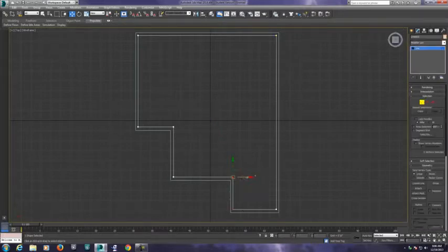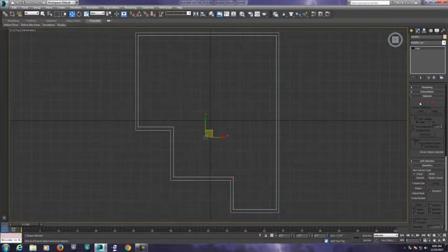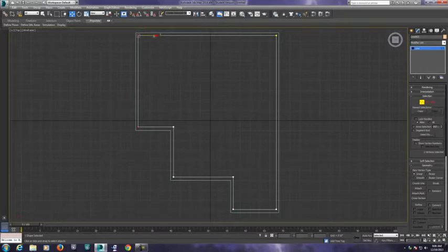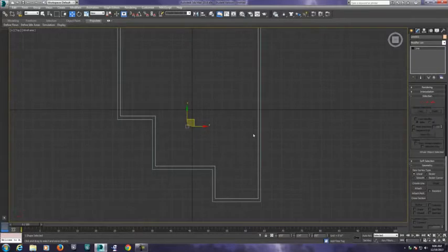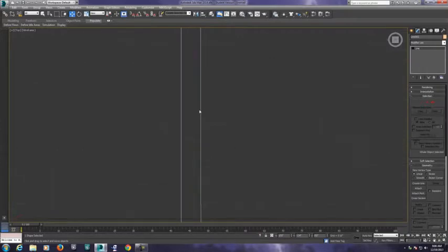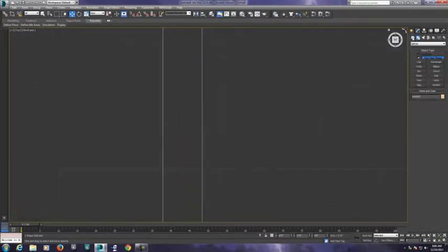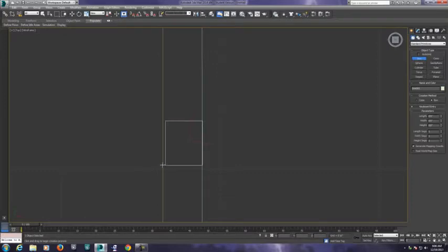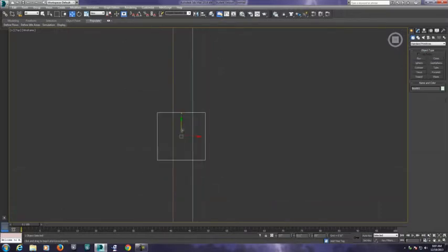And again, if somebody gave you exact dimensions, you might want to draw some lines and use some tools to lay out the actual size of the room first. And you know, the exterior and interior walls, there's typically about a 6-inch gap there. So we could test it out and say, all right, let's create a little box here as a guide. And I'm going to just make this box 6 inches by 6 inches by 6 inches. And that guide is going to let me know if my walls are offset enough, and they're definitely not.